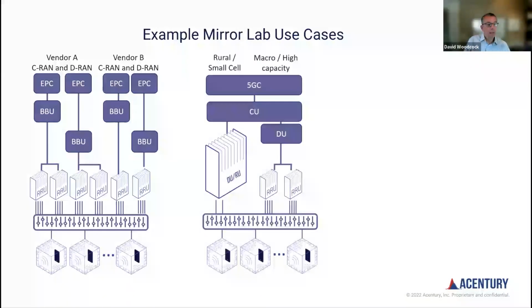The next example is a 5G operator that's replicating their dual split implementation in the lab. It looks like we have a 5G site on the left there in a split 2 configuration, which is suitable for delivering service in places where the mid-haul performance isn't great, like maybe a rural area. It could also be for delivering higher capacity services where you need some baseband processing near the edge, such as high traffic areas or in buildings. The right-hand side is a 7-2 split, maybe using mid-band spectrum because I see 4x4 MIMO here. These are probably for wider area coverage needs.